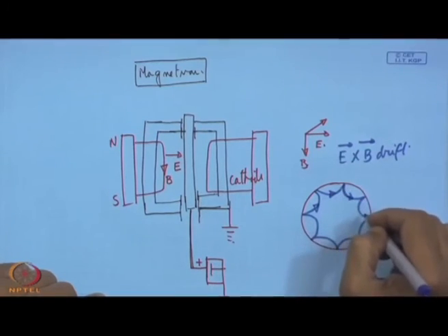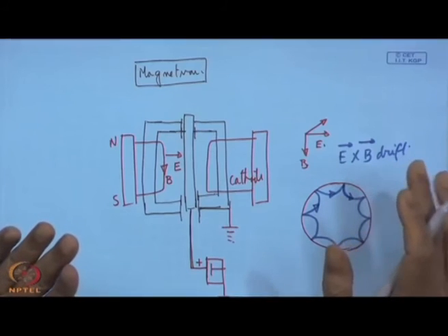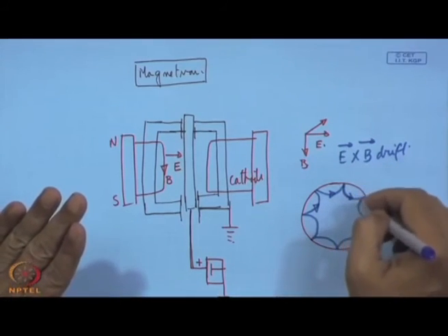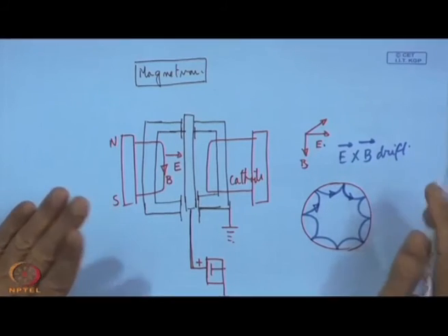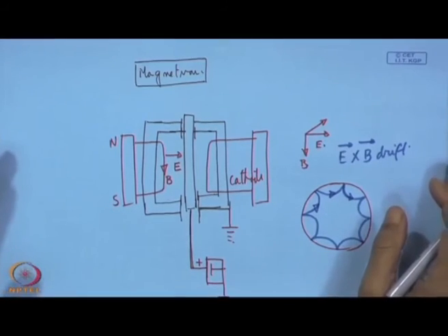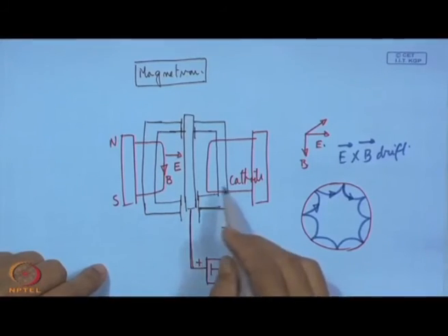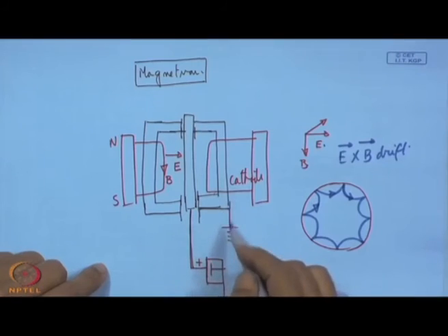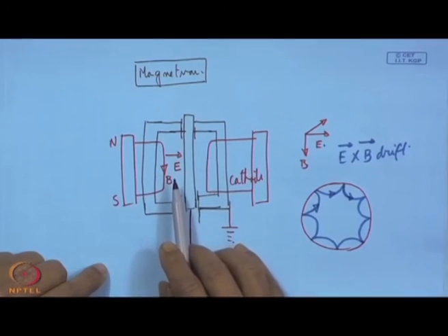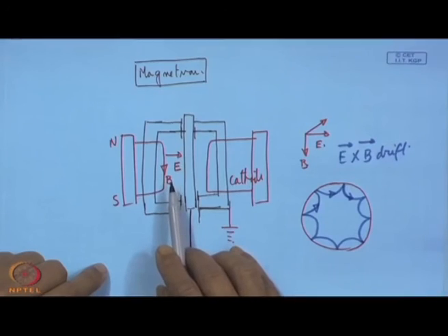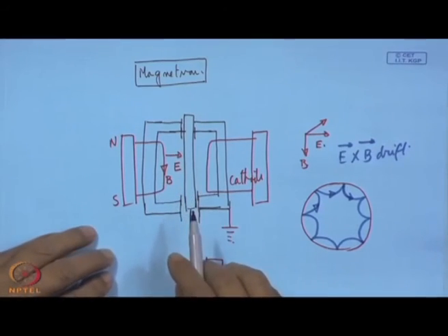That means its path is longer, and these electrons are more efficient in that they have a longer path, and in this longer path they have a fair chance of hitting one neutral and ionizing it even with low pressure. So, this is called an inverted magnetron, because here the anode is positively polarized and the cathode is grounded, and this inverted magnetron type gauge is also used for very low pressure measurement.